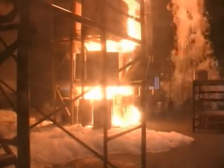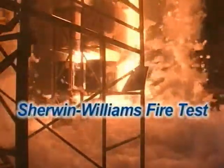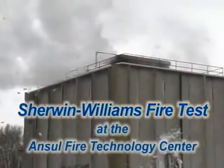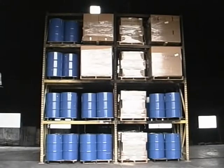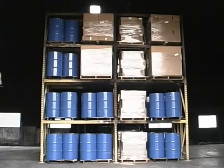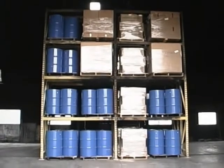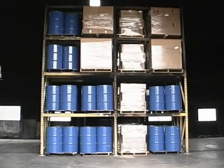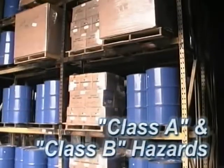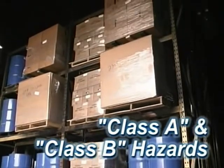To determine the viability of using total flooding high-expansion foam systems for their rack storage warehouses, Sherwin-Williams asked Ansell to run full-scale fire tests at the Ansell Fire Technology Center. The 17-foot-high storage racks were assembled in Ansell's large indoor test facility and stocked with corrugated cases containing 720 gallons of mineral spirits in 1-gallon F-style plastic containers, representing a Class A combustible and Class B flammable liquid fire hazard.